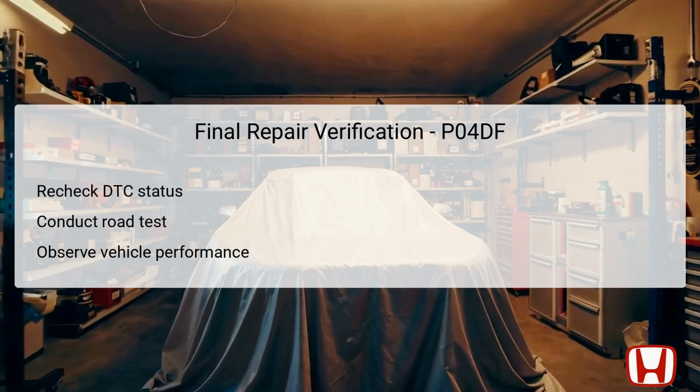After completing the repairs, a final verification process is essential to confirm that the issue has been resolved. Start by rechecking the DTC status using the Honda Diagnostic system. This step ensures that the DTC P04DF is no longer present. Following that, conduct a thorough road test to evaluate the vehicle's performance post-repair.